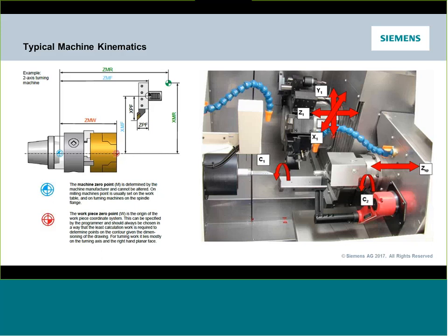And then we have on our right our Z, in our case before we were talking about Z2, that would be our sub spindle, and that can be slid or positioned over to the main spindle for doing part grabs. And that's the big thing we're going to talk about today, is really how do I handle part transfers, part cutoffs, how do I work with this sub spindle.